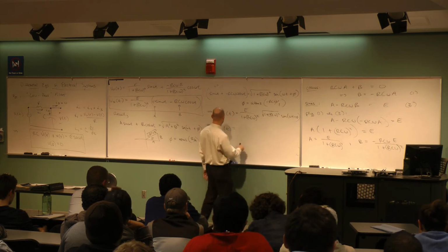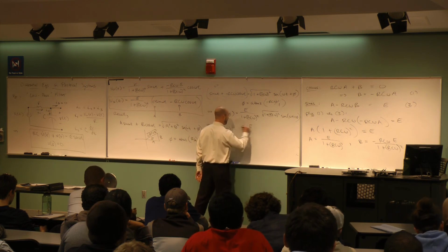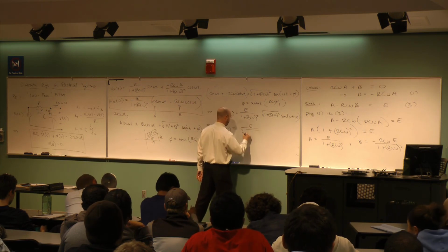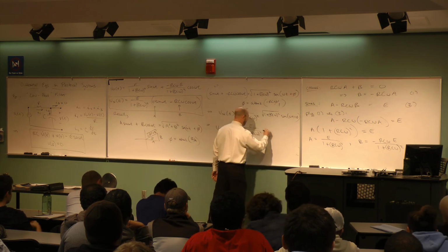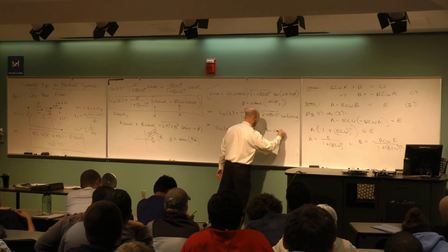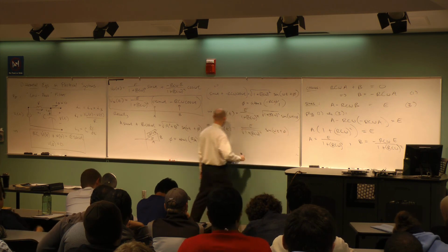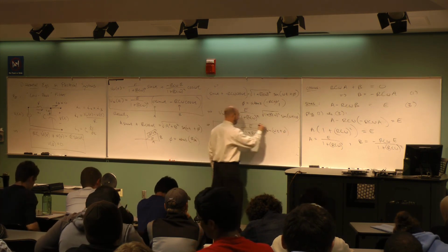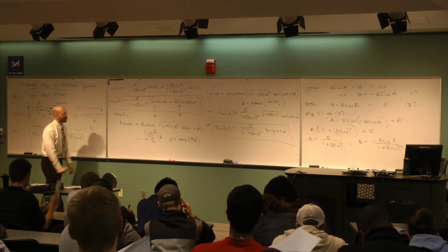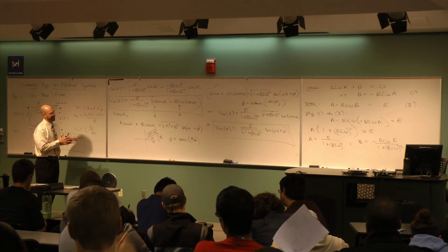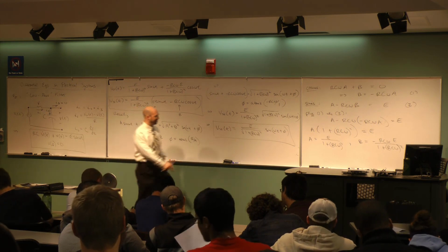Yeah. And the answer is yes. So don't I really just have E divided by the square root of 1 plus RC omega squared, times the sine omega t plus phi? Like that. Bam. That's the steady state. Worth 5 more points on your final exam. That's a well-earned 5 points.